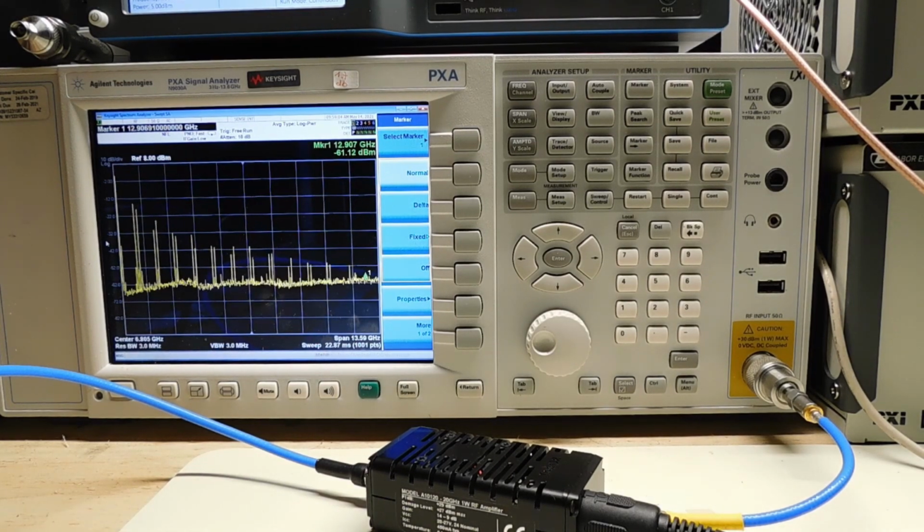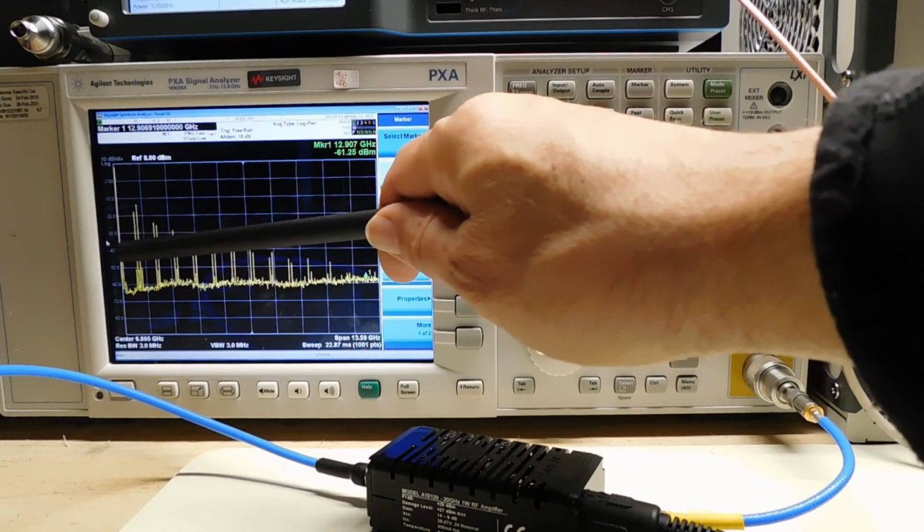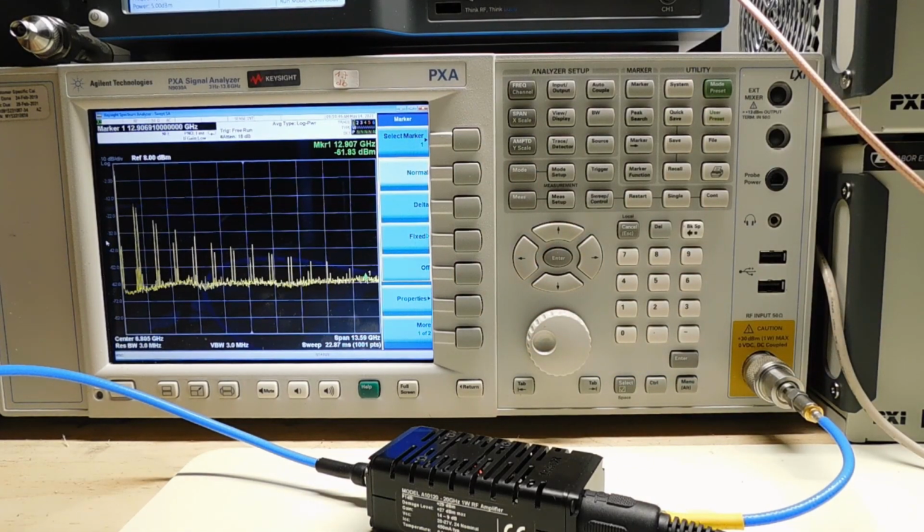One of the things that the Proteus arbitrary waveform generator family have is a very wide output filter, 9 gigahertz. So this is one of the reasons why we see all these different spectral components going all the way up to 9, 10, 11 gigahertz. So the roll off is not just sin x over x, it's actually the roll off of the filter that we are observing as well. Now, if we just want to generate a really pure 75 megahertz signal, or maybe 100 megahertz, 200 megahertz, depending on the quantum system that we're trying to generate signals for, the bandwidth of that system may be wide enough to allow some of these components to creep in, thus creating some distortion.